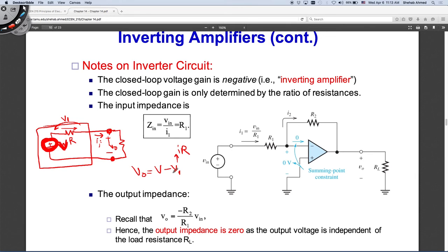So now what's going to happen if the current increases? Yeah, exactly. The output voltage will decrease. So the more you increase the current, the output voltage will actually decrease because of what is called an output resistance of the circuit that's feeding your load.